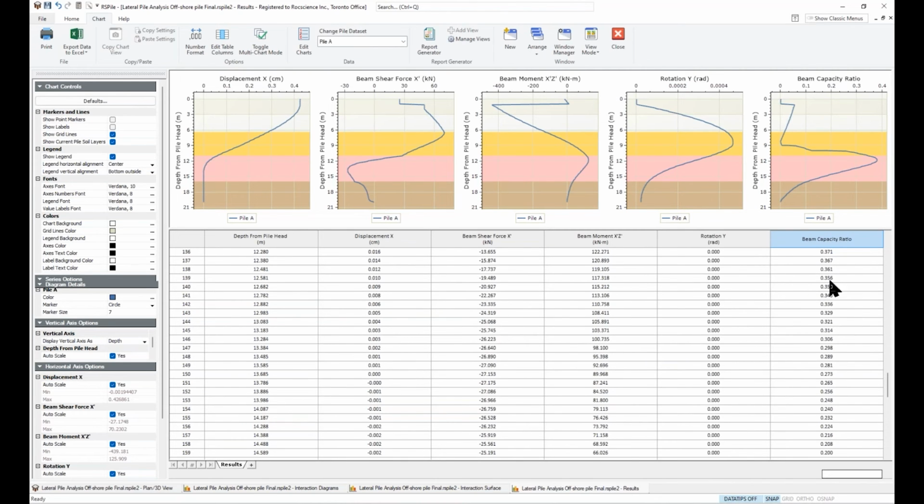Why did it increase again? Because the casing is finished. After the casing, the bending moment capacity decreased, so the applied moment divided by the bending moment capacity got a higher value. If this value exceeds 1, exceeds unity, the cells will turn immediately into red cells, indicating inadequacy of the section.